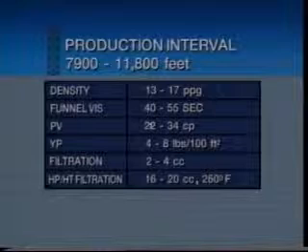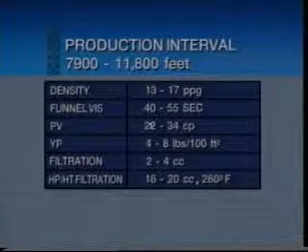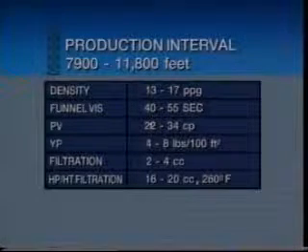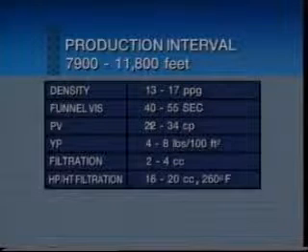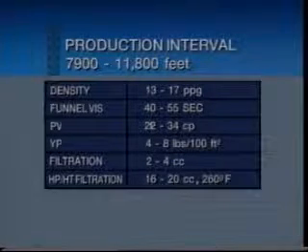Depending on the nature of the producing formation, a solids-free weighted brine may be circulated into the hole prior to perforating the casing to improve the chances for open high-capacity perforations.